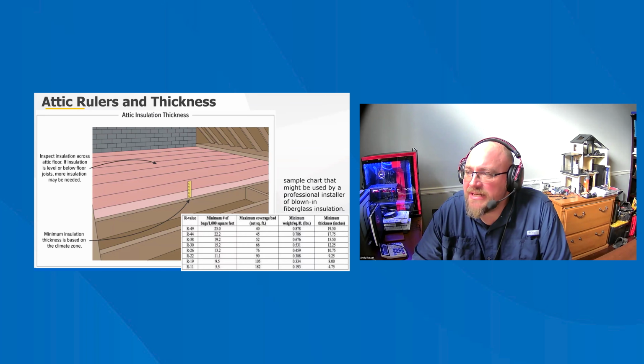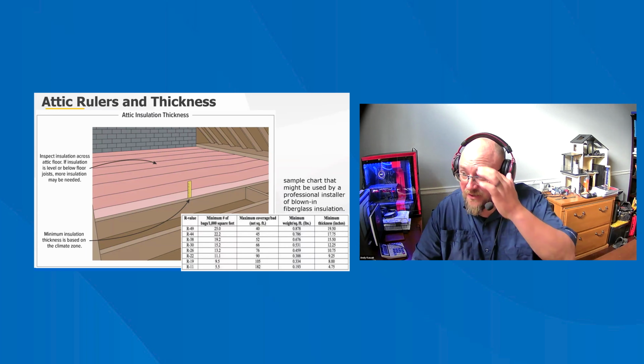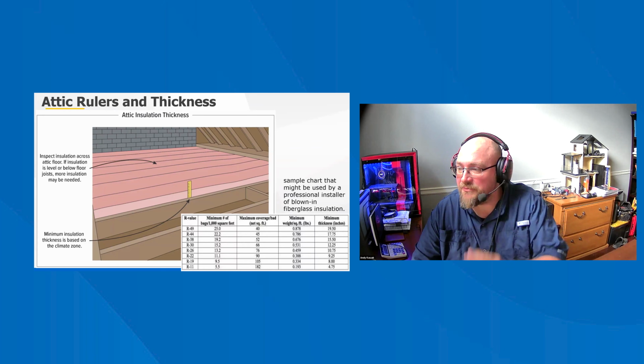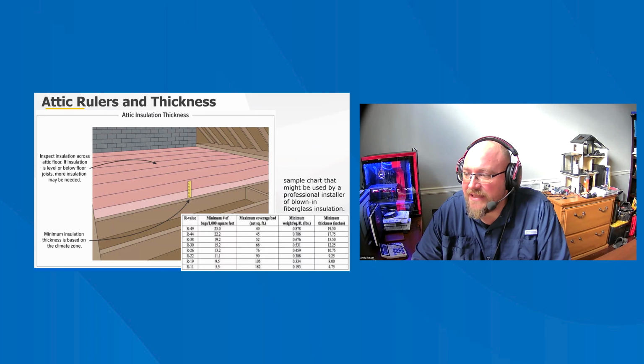If the attic has blown-in insulation, check the back corners in hard to see and hard to access areas. It is common for these areas to have insulation installed that is too thin. Insulation should be evenly distributed throughout the attic with the correct density and depth. Additionally, baffles should be installed to prevent blocking the airflow from the attic vents, particularly at the eaves. The insulation should be blown all the way to the top plate of the exterior wall.